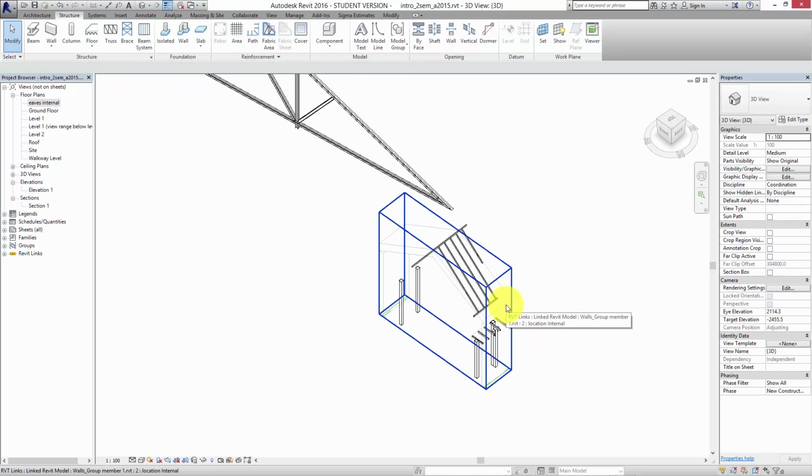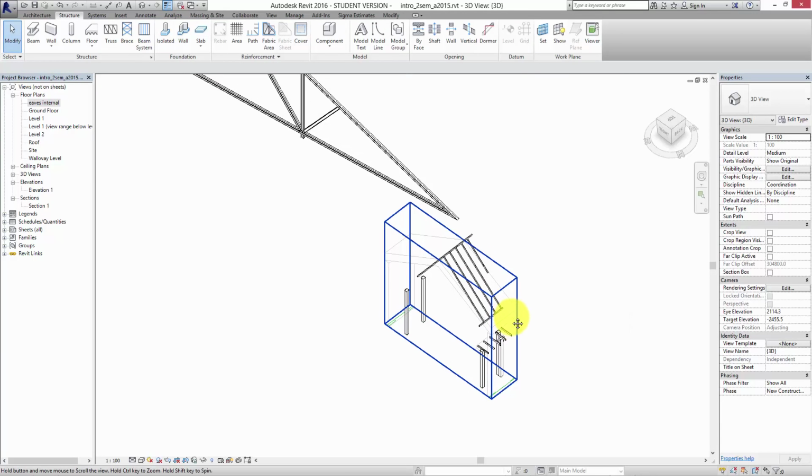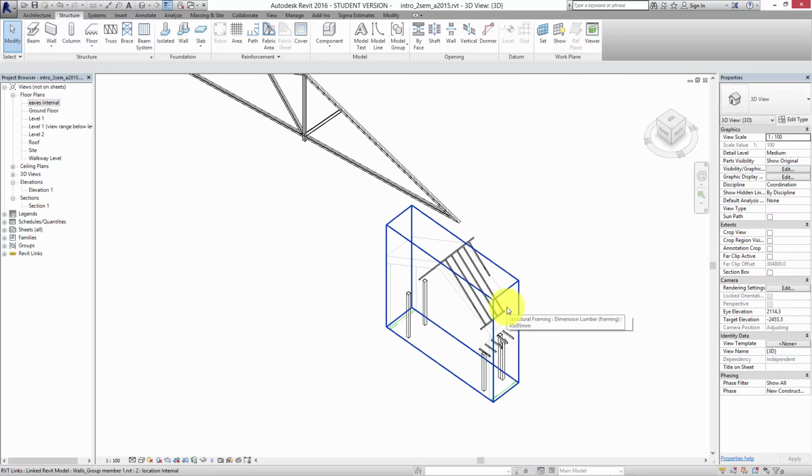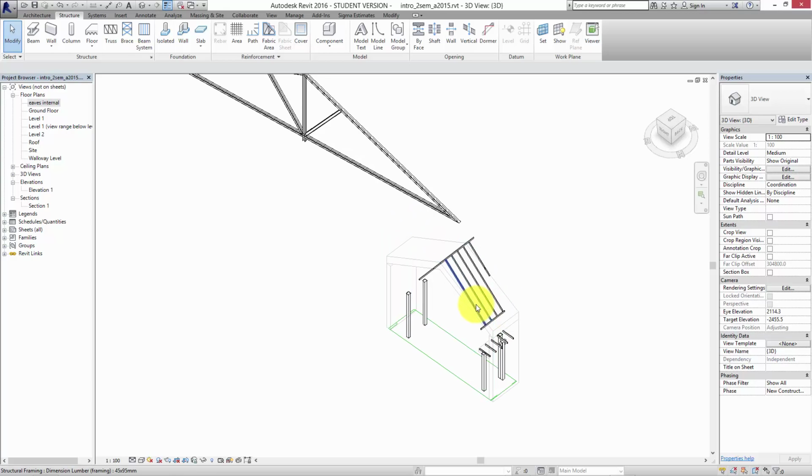Is that okay? Yeah. The individual purlins that you have in there, as in the beams that run along kind of halfway up the truss, you need to place them according to a level. That would be the best way to do that. So you set up a level for those purlins. Over this rafter, as you said, there is another beam in between. Yeah.